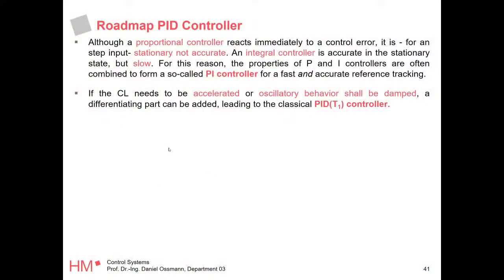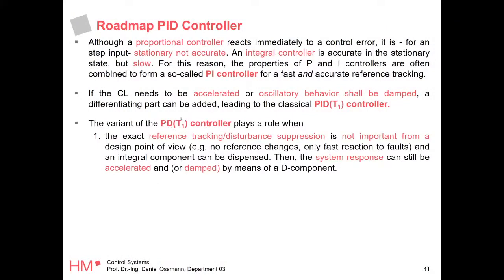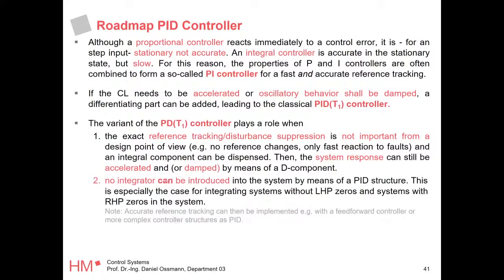The remainder of these slides are when we leave out the integral element. You could say, okay, I don't care about steady state accuracy or disturbance suppression, right? Then you just leave out the integral element. But you still want to damp the system, then you need the D. And the second idea when to use a PD controller is when you are just not able to introduce an integral element because you already have some integral in your system.